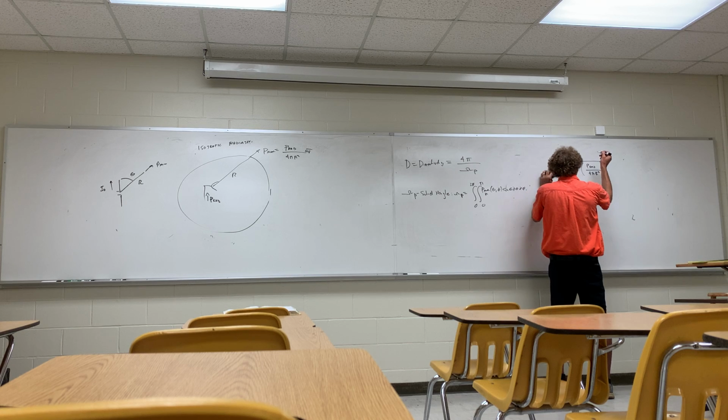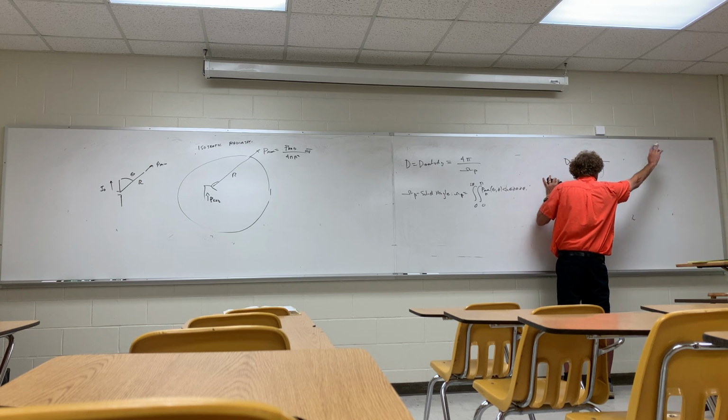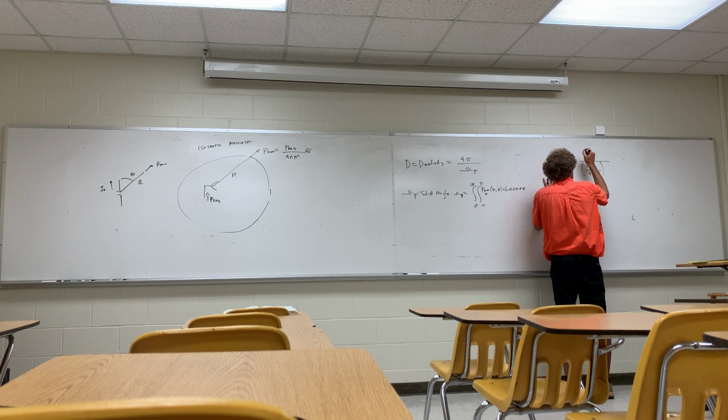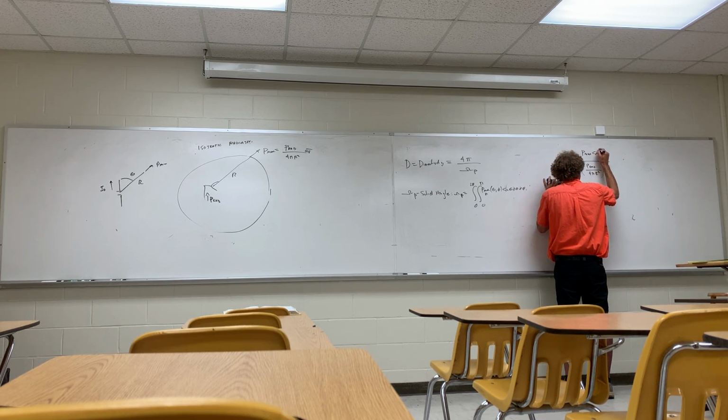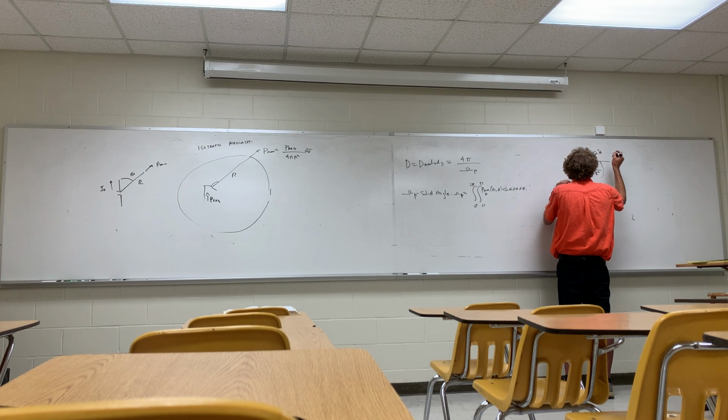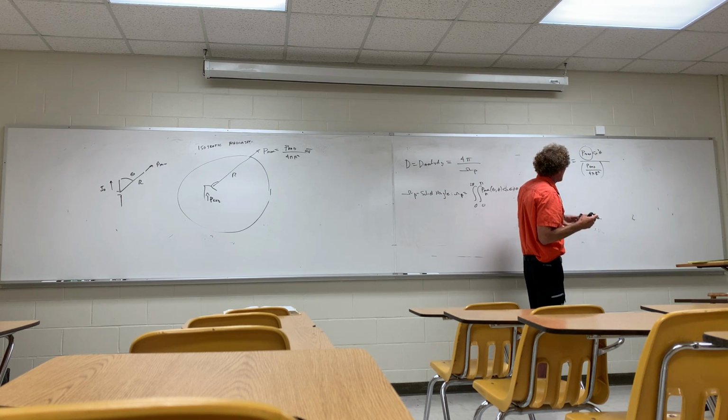Up top, now you're gonna have to find the power density of your actual system. And remember, I wrote something over there some time ago, and I had, I'll just call it P max here. P max times the sine squared of theta. And this P max had a bunch of terms in it. Well, when you actually go about doing this, you're gonna see P max is gonna have an R squared in it too, and the R squareds will cancel. The 4 pi will come up top, and then P max can be written in terms of P rad.